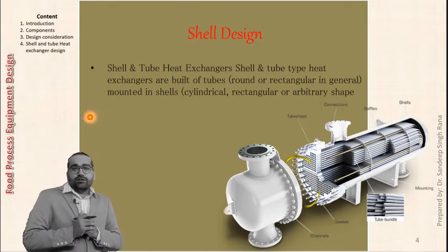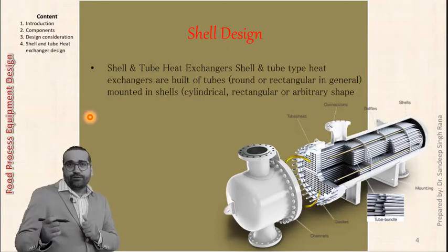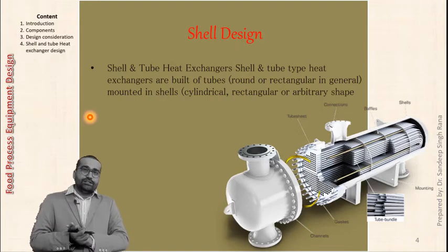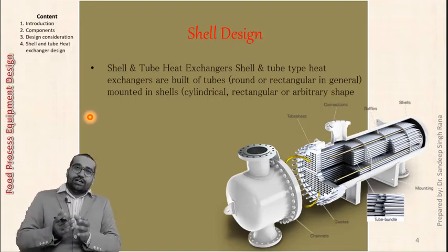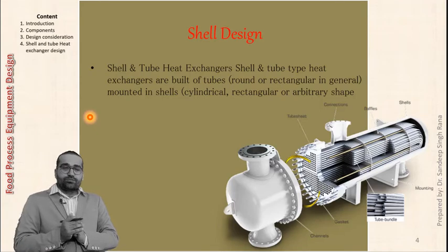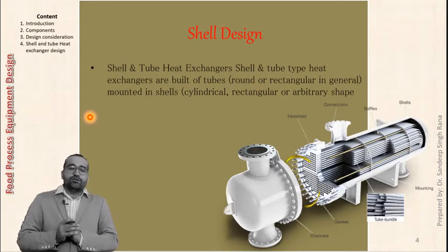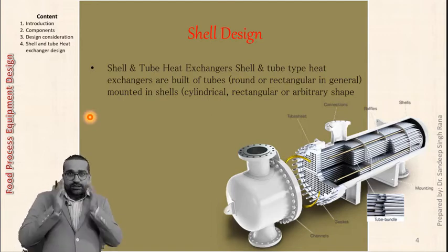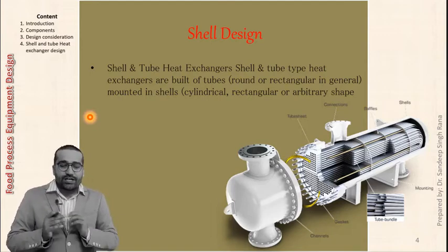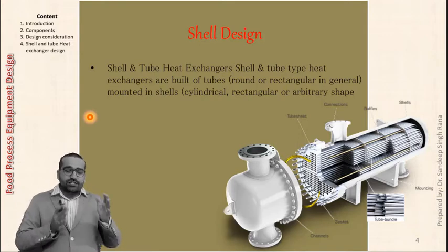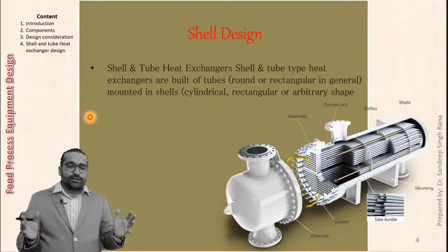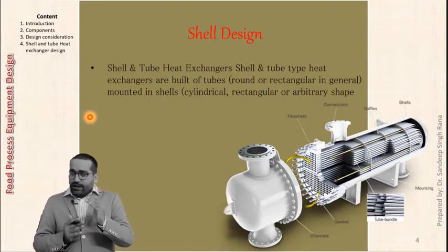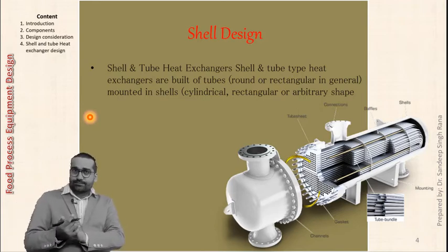If we start with the design of shell and tube type heat exchanger, first comes the shell design. We have to design the shell. How do we design the shell and what is a shell? Let us discuss here. So shell is the container for fluids and the tubes placed inside it. It works as a container. And shell diameter should be selected such that it gives a close fit of the tube bundle. So we have to design here for diameter of the shell.